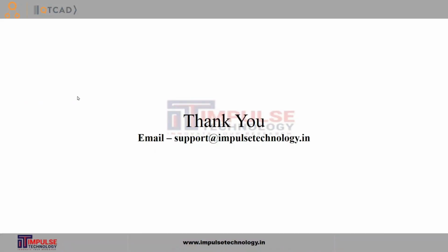Here our simulation is completed. In this tutorial, we revisited the nanowire structure, focusing on the interplay between Poisson and Schrödinger simulation. In analyzing the quantum dot region, we examined how the conduction band forms a potential well and how classical and quantum approaches influence the result. By incorporating the Schrödinger equation within the quantum dot region, we highlighted the importance of considering quantum confinement effects in nanoscale devices or structures.